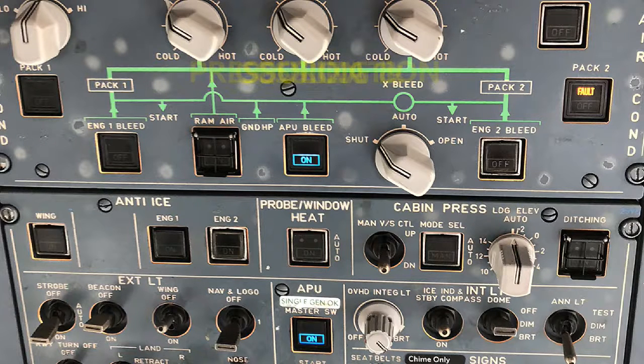So what's happening when that push button's on is, if the temperature in the supply duct goes above 190.4 degrees Fahrenheit, and by the way, some of these are indicated in degrees Celsius on the actual panel, so you may not see degrees Fahrenheit, just Celsius. The conversion of 190.4 degrees Fahrenheit is 88 degrees Celsius. If the temperature goes above that, the valve's going to close automatically. And of course, if the push button is pushed off, then the valve's going to close. Anytime there's that temperature issue, the system's going to protect itself.